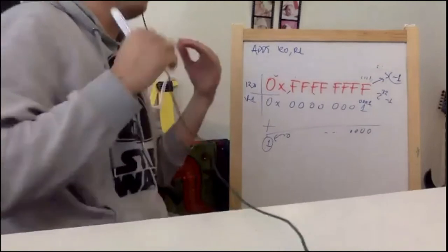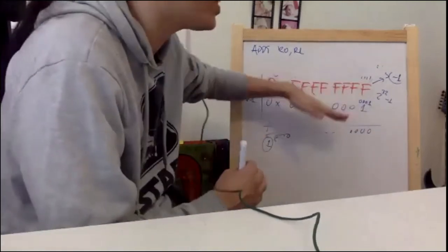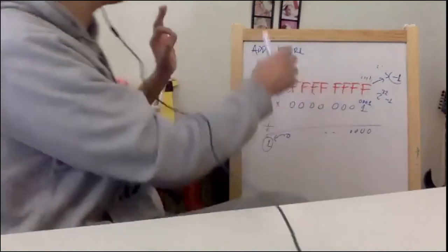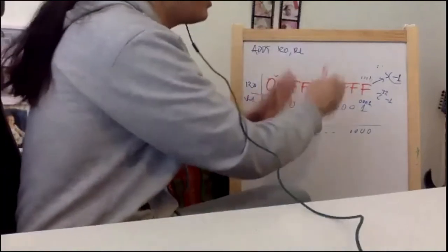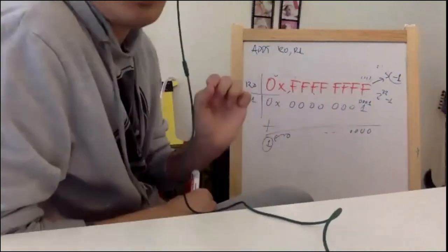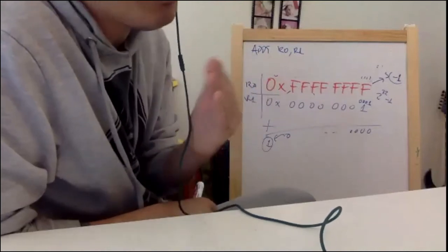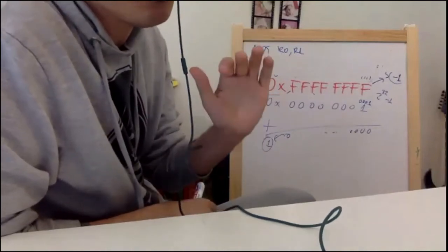Okay. So the first thing I do is I make the summation without thinking if it is signed or unsigned. I make it just the summation. Sum these hexadecimal numbers up. And if there is one getting out, I'm saying that there is either carry or overflow. But which one, I don't know yet. Maybe both, because in the previous case, it was both.